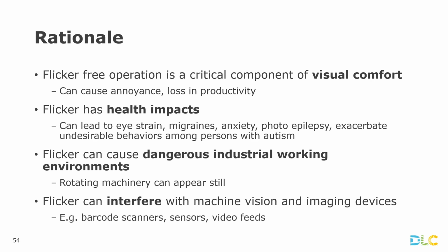And flicker can cause dangerous industrial working environments by making rotating machinery appear slowing or still when the frequency of flicker approaches the speed, or like the RPM, of spinning parts, which can clearly be really dangerous in that environment.